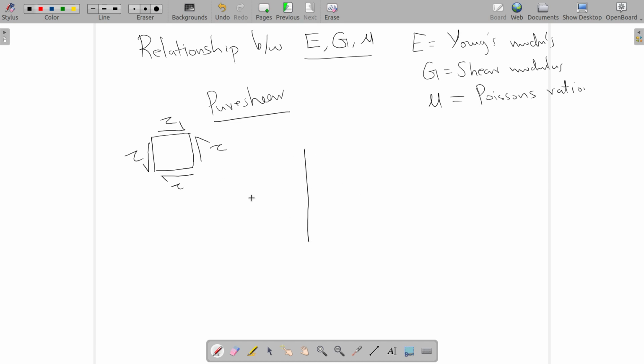How will that look in a Mohr circle? Wherever you keep the diagonal, you will always have some value of normal stresses. How do we make the normal stress 0? Only one state of stress will give you that case.